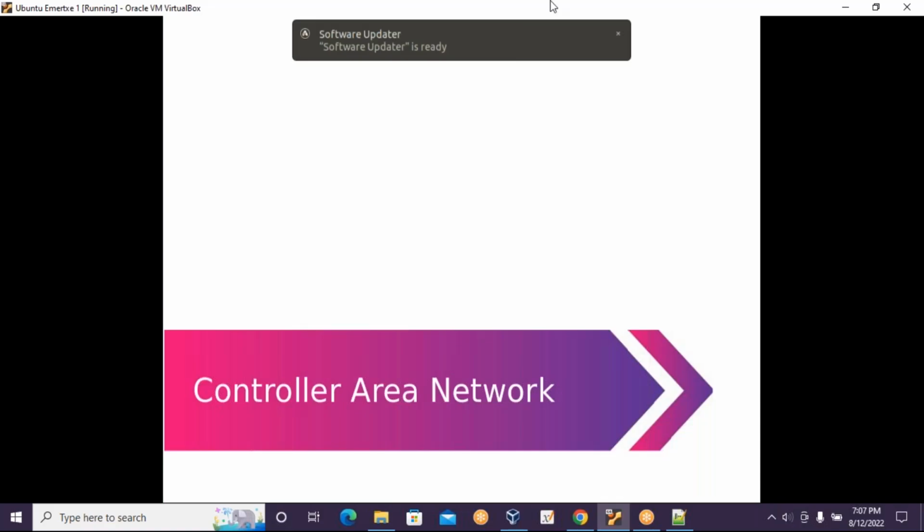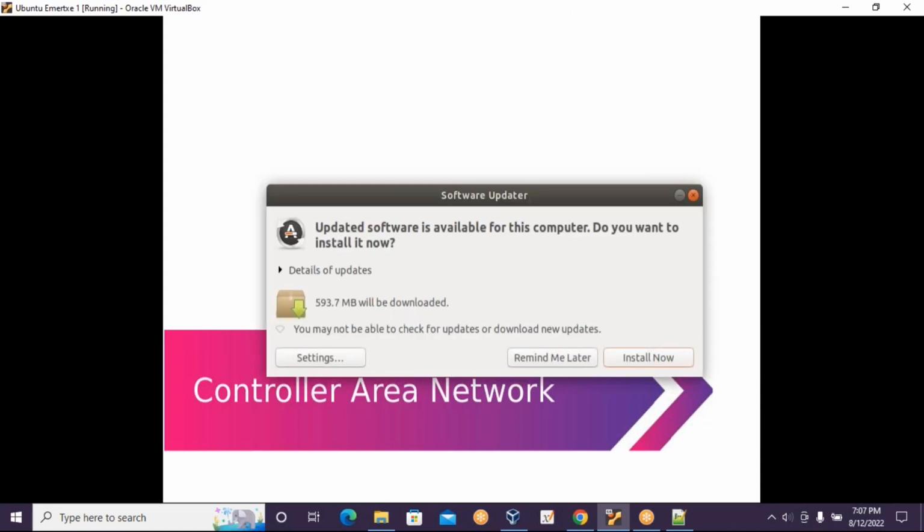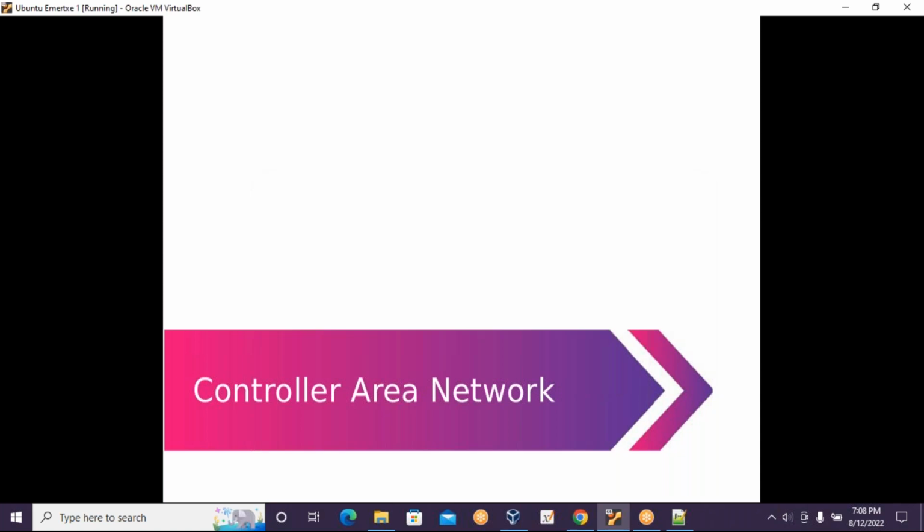In the previous class, we were discussing the things related to the I2C protocol. So we were actually into the program where our microcontroller, the PIC16F877A, had to communicate with the RTC. The RTC was DS1307. So the two chips which are on the same board had to be communicating with each other, and hence we had to go with the intra-board protocol, which was I2C protocol.